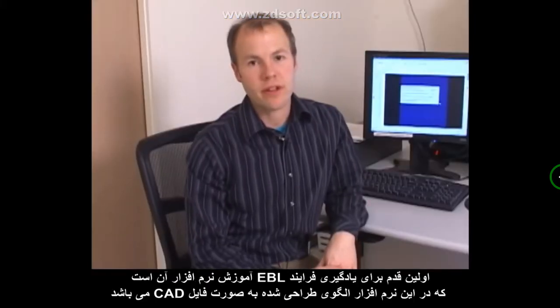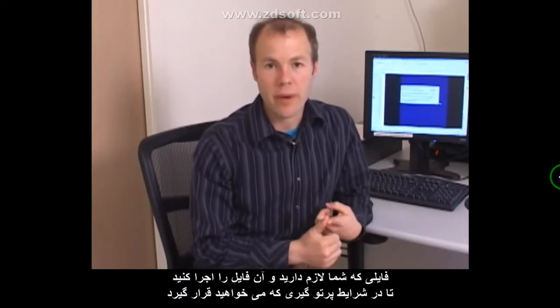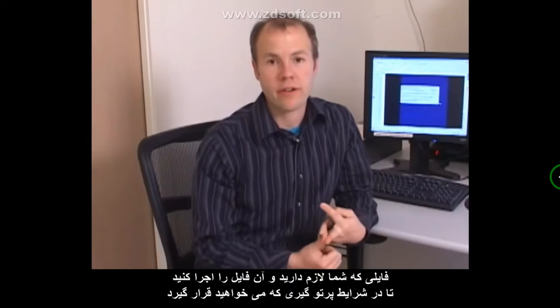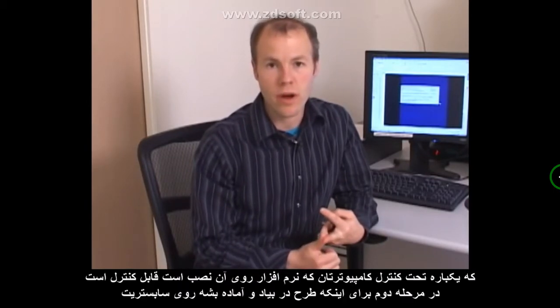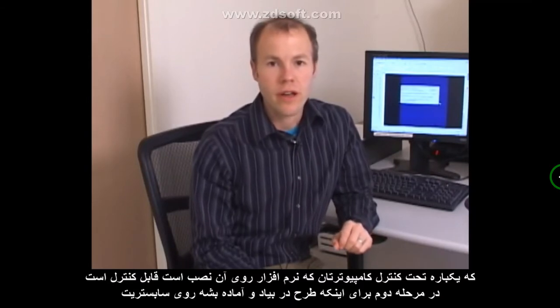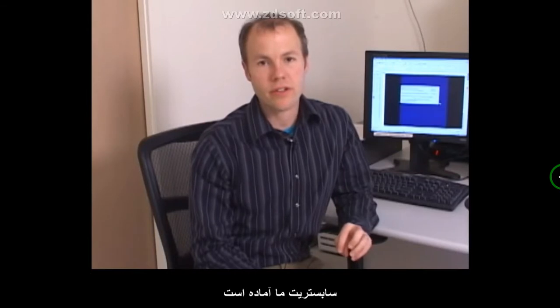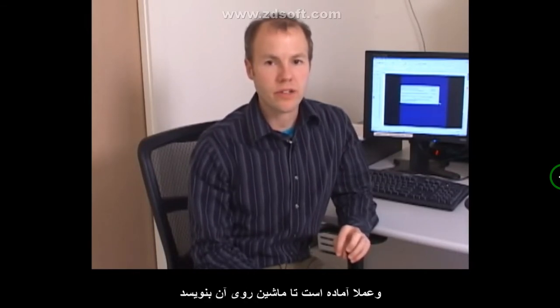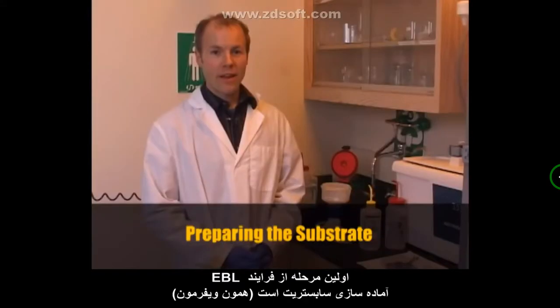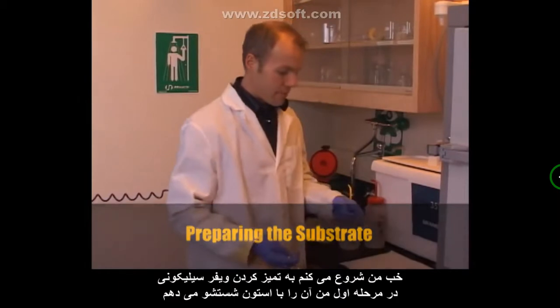The first step in EBL training is to learn the software. Generate a design CAD file for the pattern that you want, and then a run file for the exposure conditions that you want. That can be done on your own computer once you've installed the software. The second step is to come in and prepare the substrate. Once the substrate is ready, you can book some SEM time, come in and actually do the writing on the machine. The first step of the EBL process is preparing the substrate.